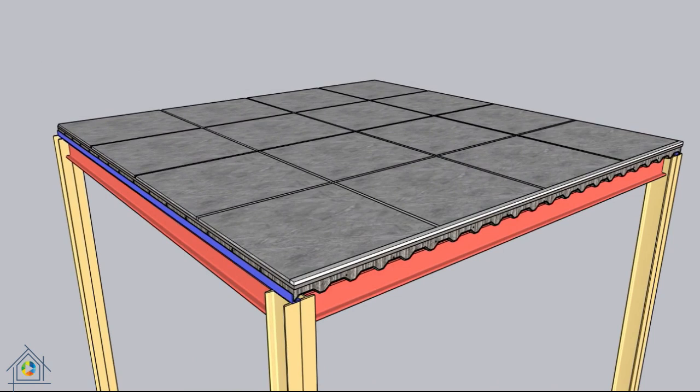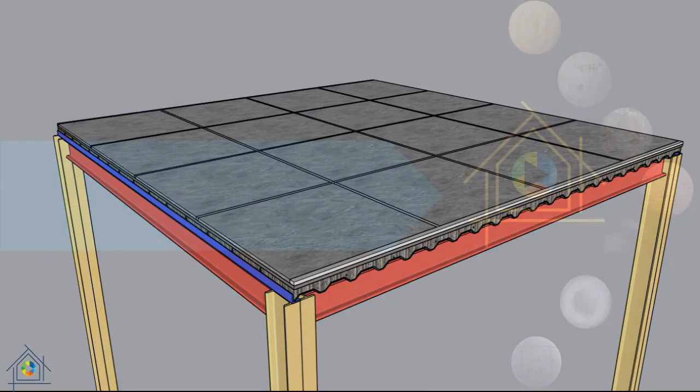Due to the smoothness of the bottom surface of the stones, a groove must be created under the stones for adhesion to the mortar. Cement grout is implemented between the joints of the floor stones. The distance between the stones is between 5 and 20 millimeters.